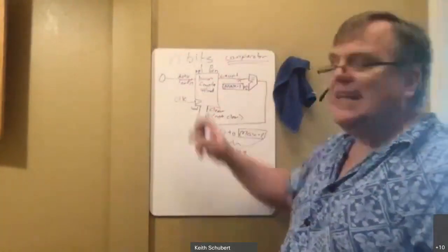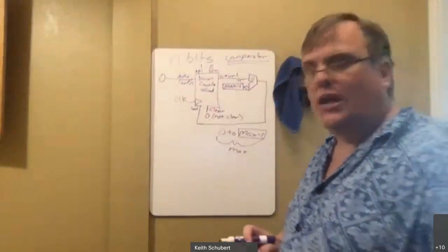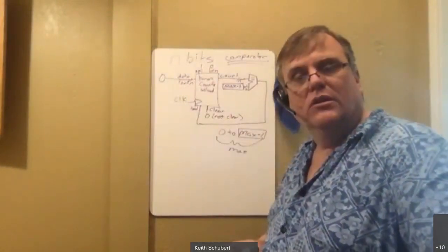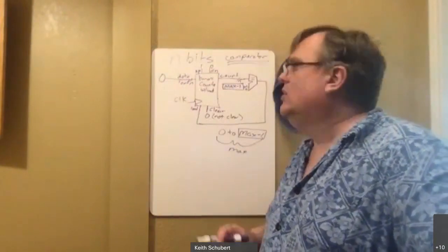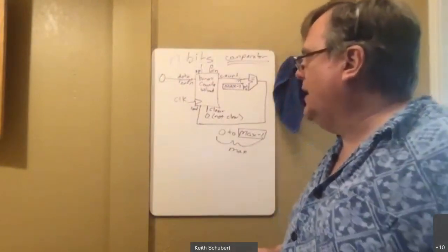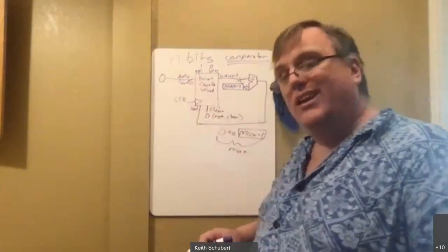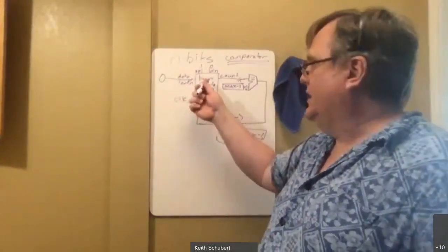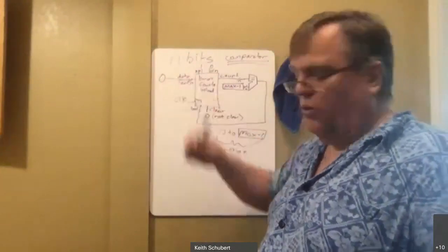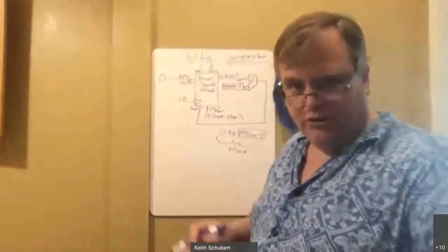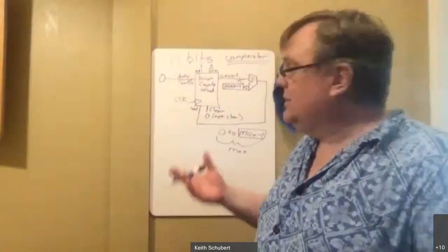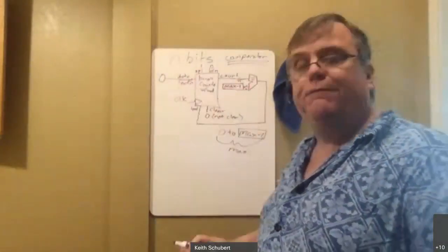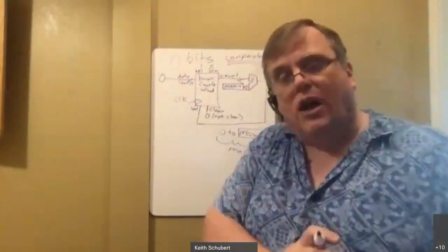And notice I didn't have to do anything different than I did last time. I can literally use my synchronous binary counter that we had. If my synchronous binary counter doesn't have a load, all it is to add it in is to put a mux. It either gets the count plus 1 or we load a 0 in. And I'll show that here in a sec. But it's very easy to build this circuit. All I'm doing is configuring what we built last time.